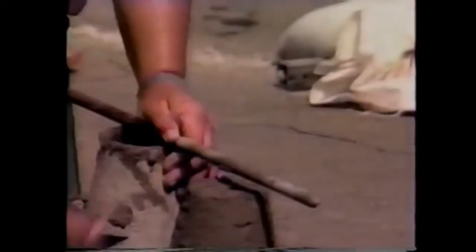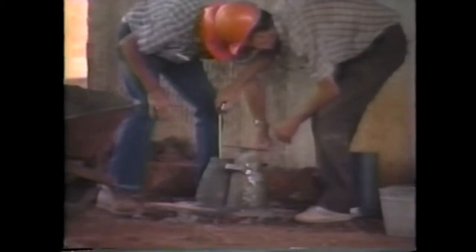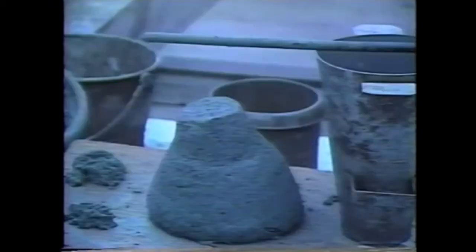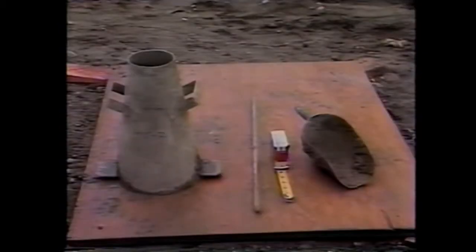Next on the list is the slump test. Variations in slump generally indicate that changes have occurred in the properties or proportions of cement, aggregates, water, or admixtures. The equipment needed for slump tests includes a standard slump cone, a standard tamping rod, a scoop, a base, and a ruler or measuring tape.